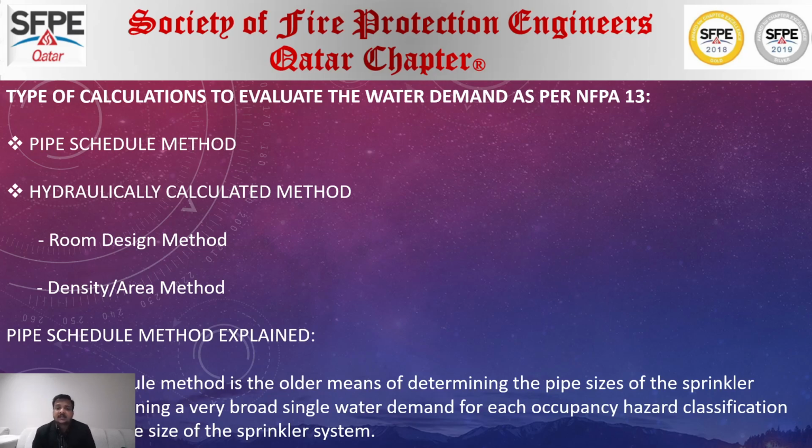As I have mentioned earlier, two methodologies, pipe schedule and hydraulically calculated method. So what is pipe schedule method? The pipe schedule method is one of the oldest means of determining the pipe sizes of sprinkler system and defining a very broad single water demand for each occupancy, regardless of the area of sprinkler operation, as I have explained before. The concept of using pipe schedule methodology is that you do not have any fire barriers in a building, so the fire originated in one place can spread into another place. So you need to have an adequate amount of water to provide the sprinklers in order to control the fire or extinguish the fire.